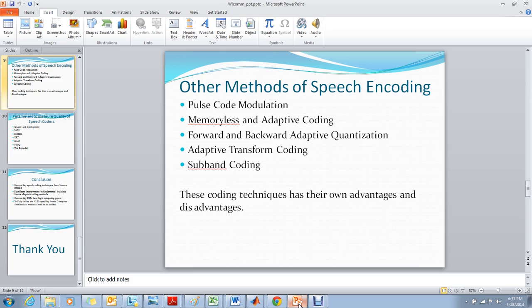Adaptive transform coders derive an input signal spectral representation and then use dynamic bit allocation to quantize the spectral coefficients. On the decoder side, the exact inverse happens and the original speech signal is reconstructed. Subband coding is where the wide range of the audio signal is split into different subbands of smaller frequencies and wideband analysis is performed using a filter bank approach, and each band signal is then mapped to a zero frequency domain and sampled at the requisite rate.